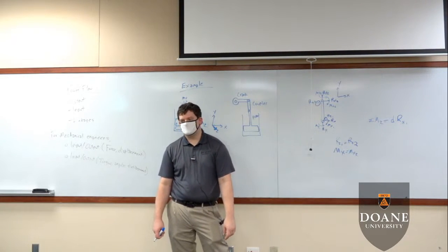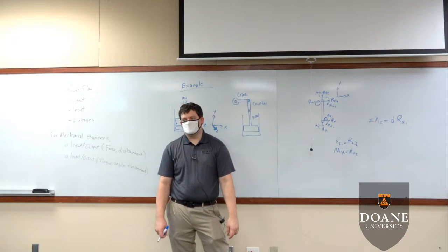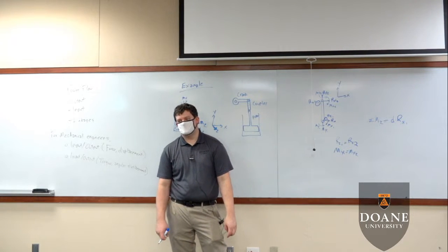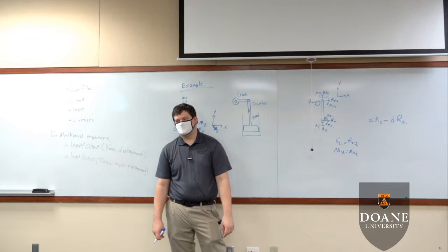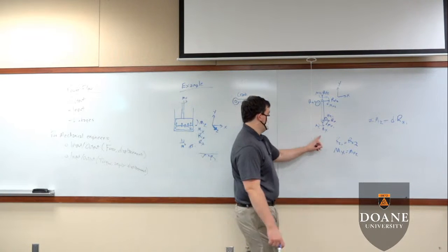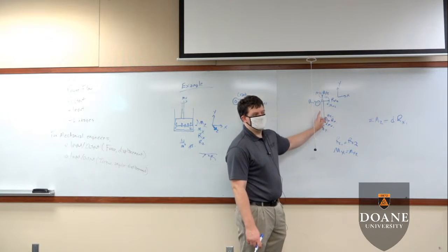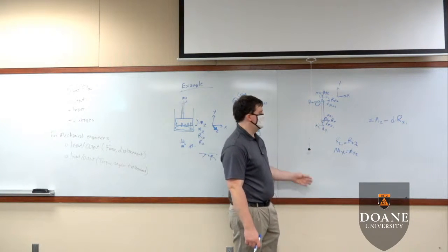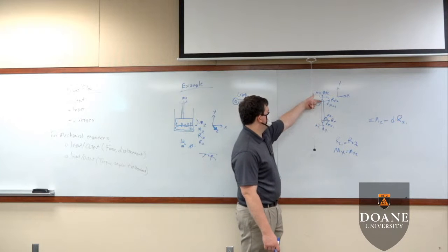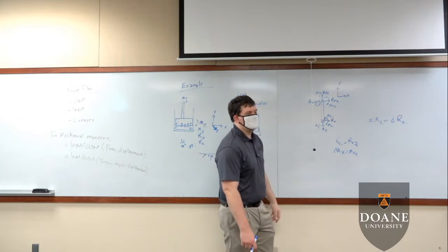Sean says no. What do you think, Daniel? No. If we have an Ry value, the Ry values are in line with each other. When they're in line, it doesn't create a moment. When they're out of line of each other, which is what your Rx values have, then it can create a moment.